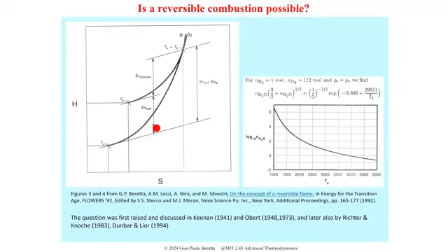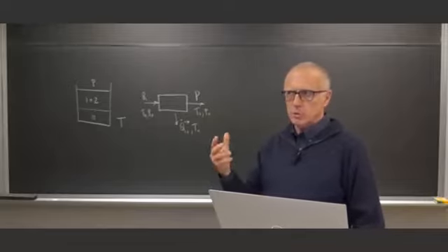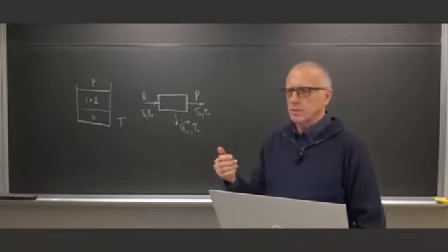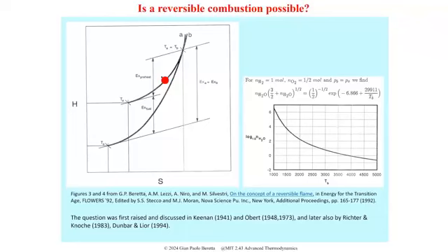But the problem in practice is that as you go above a certain temperature, any mixture will have a self-combustion, an auto-combustion limit, and it will burn by itself. And that's why we were looking for a way to dilute enough. By diluting, you reduce the temperature at which this happens, and therefore you have to go below the self-combustion temperature.